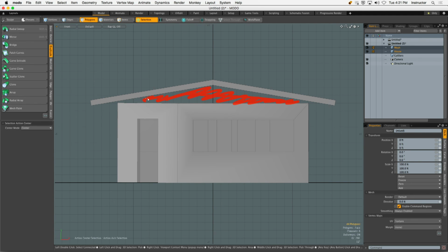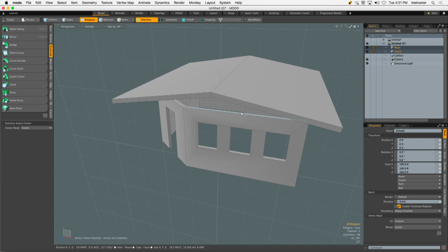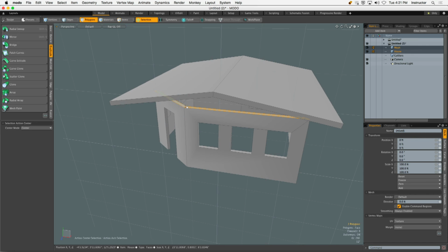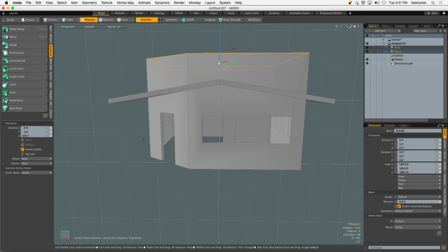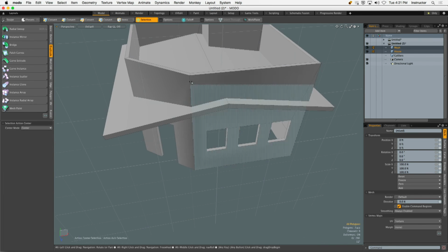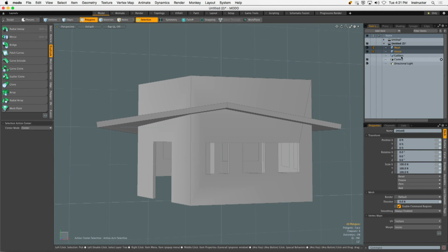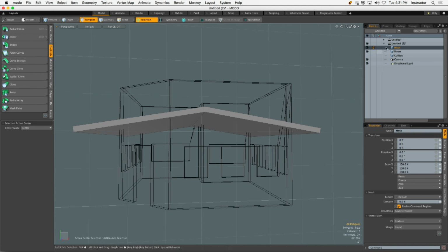Check out this. You can use the power of the Boolean system to get the end result pretty quickly. Okay? All right, let's just do it real fast. I want to grab the top of my walls, and I want to move them past the top of my roof, like that. Okay? Now, don't worry about it. It's going to look funky for a second, but we're going to use Booleans to get us where we need to go, right? This is my roof. Let's just name it roof.